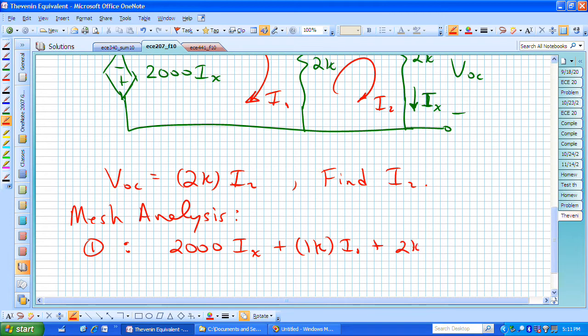And then we have the voltage drop across the 2K vertical, the first one in the middle, and that's 2K times I1 minus I sub 2, and we're back to where we started, and there's 0.